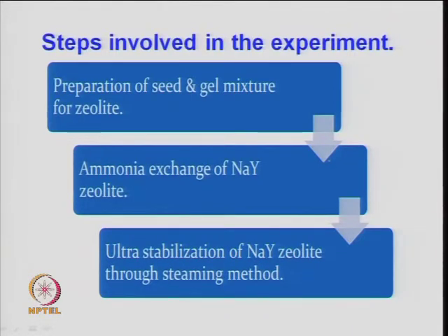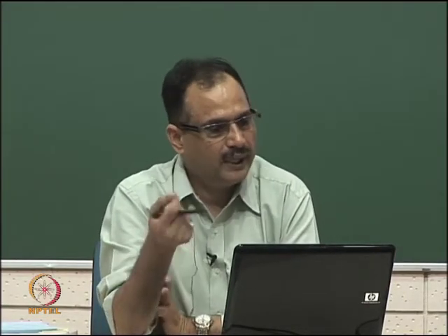So, sometimes steaming is done, right, for widening the pore sometimes, and sometimes this also provides protons to the system when you have a sufficient treatment with the steam. Sometimes de-alumination is required, right. So, a mild acid treatment is done to remove the aluminum from the framework of the zeolite. So, de-alumination is another part in the same step of the zeolite formation, because as I said, if the silicon to aluminum ratio is high, right, your concentration will be less, but strength of the acid site is more. So, sometimes you may have more loose type of acidity in the zeolite, right.